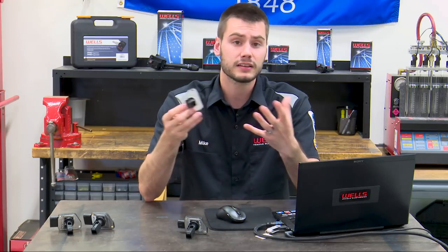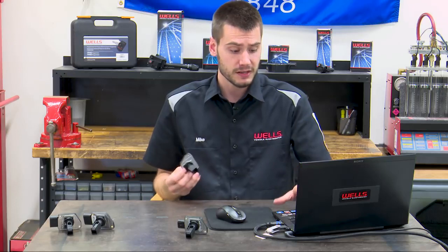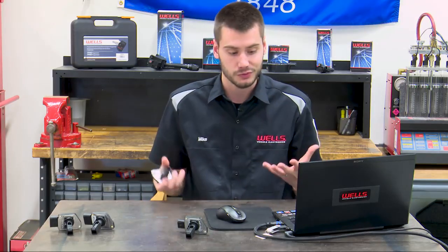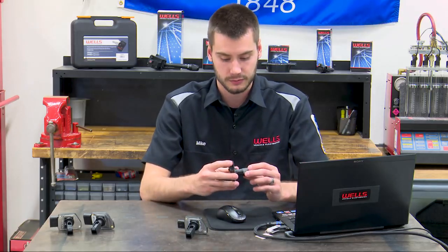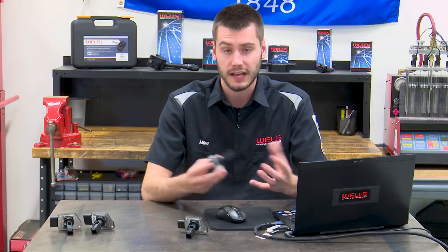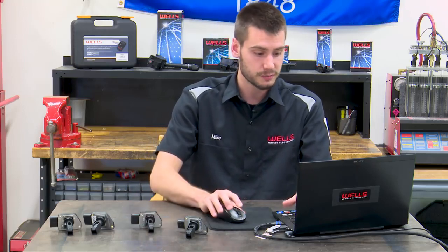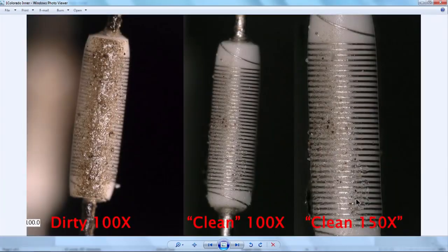So again, the option is really up to your customer, but if you ask me, judging by these pictures here, is there really an option? You don't put new ball bearings in a wheel bearing, right? You don't do that kind of thing. Why does cleaning a mass airflow sensor, why is that something that's even possible? The element's damaged. I mean, look at this picture. This element here is damaged.